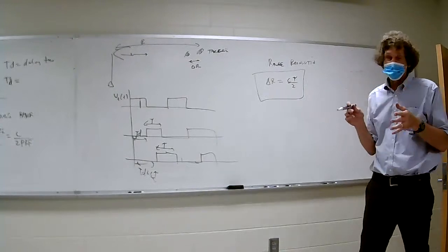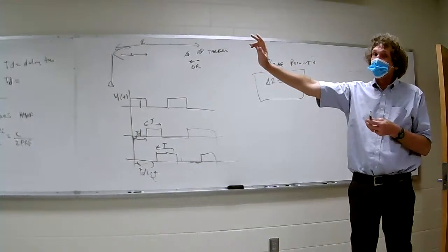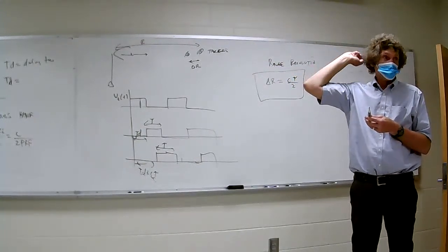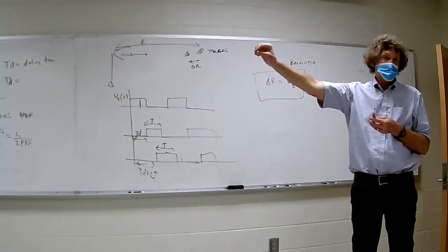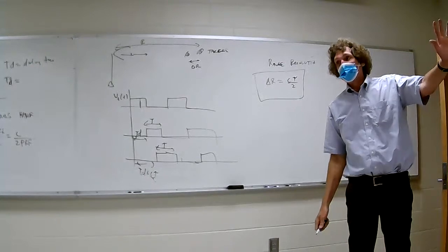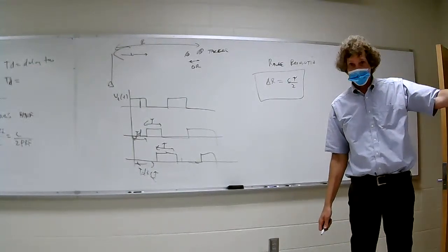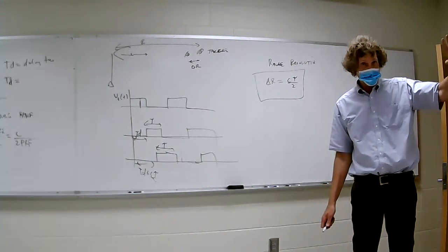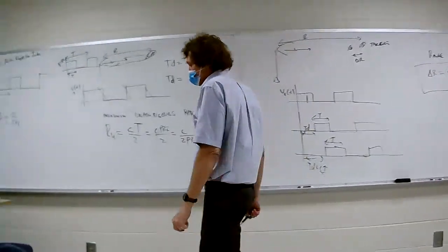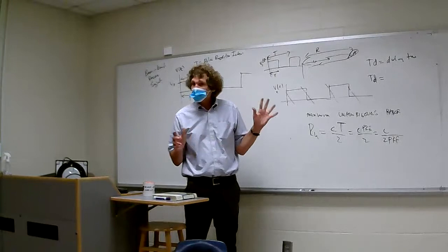That's one of the things about this radar resolution. It becomes very important. Some people will say, well, when I look, I can tell there's one. You don't understand with radar. The only thing you see is a glimmer, you might say. Think about things miles and miles away where you might see a glimmer from the sun. With radar, you basically see a return that gives you no features about anything out there. Generally speaking, you're going to get a return strength and you know the relative strength of the return. But that's about it. It's very hard to figure out anything more about the target. So that's the range resolution.